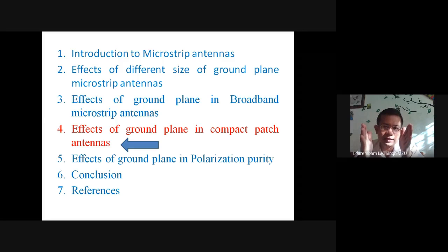but with certain cuts on this antenna ground plane or maybe on the patch itself, it is going to work from 5 down to 2, like that. But suppose if it is a conventional 2 gigahertz antenna, then the size will be like this. So the 5 gigahertz one, after introducing some cuts and slots, will be able to work at 2 gigahertz. So it is nothing but overall a compactness of the patch.